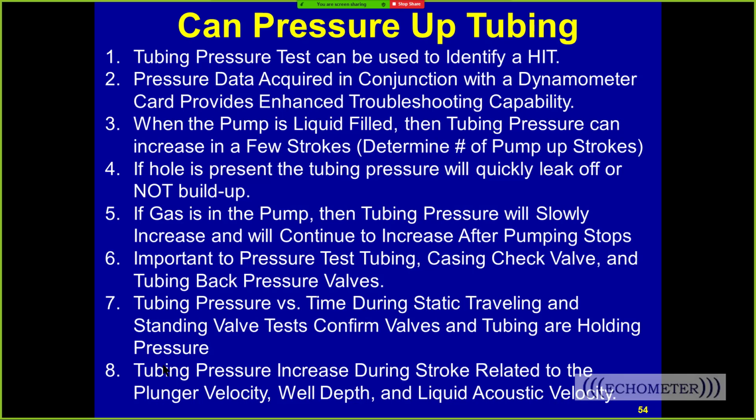And so if your well's 8,000 foot deep, it takes 2 seconds for the pressure wave from the pump to hit the surface. If your well's 4,000 foot deep, it takes 1 second. And so the way the pressure at the surface responds from pressure increases at the pump are related to the pump depth. So if you are in one field and have a rule of thumb about a certain time, and the pressure at the surface behaves a certain way, it really is depth dependent. You need to be cautious about those kind of rules.